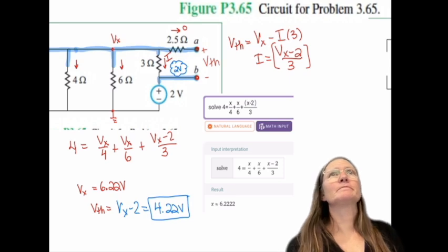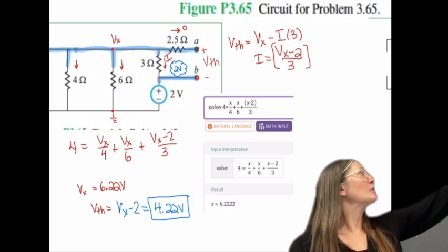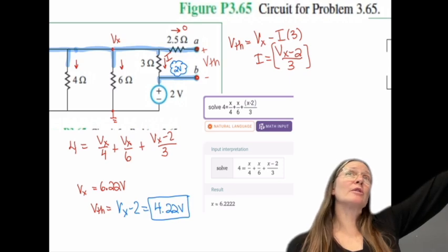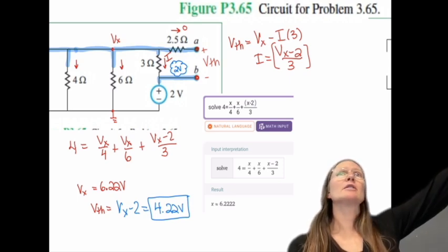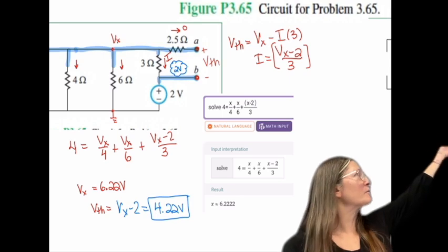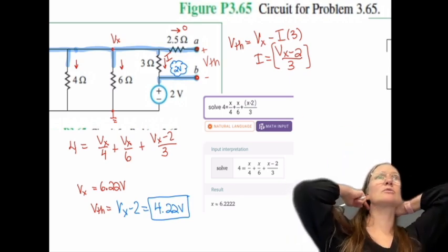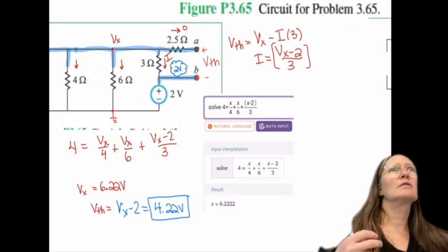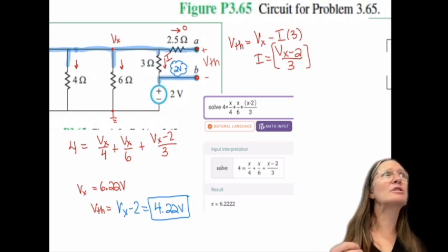Is it always, I guess if it's 0 current, then still... Yeah, there's zero, you understand that there's 0 current there because it's open. And if there's no current, there's no voltage drop across there. So whatever is at the node before it is the same as the node through that resistor, which is all A. Does that make sense? Other questions?